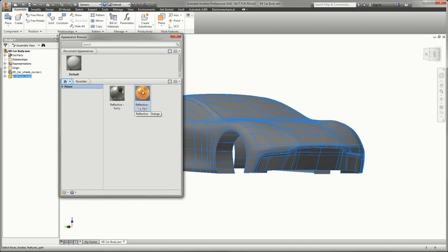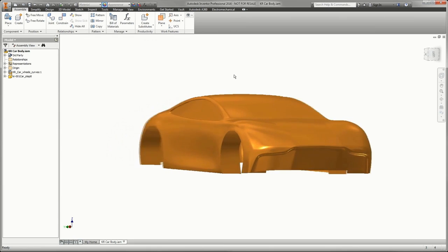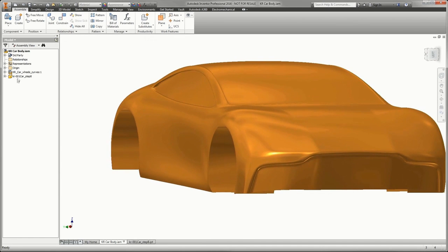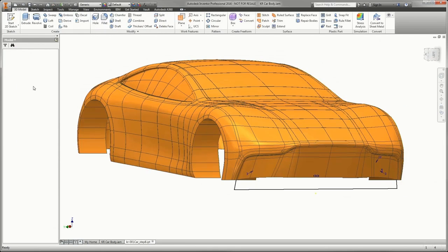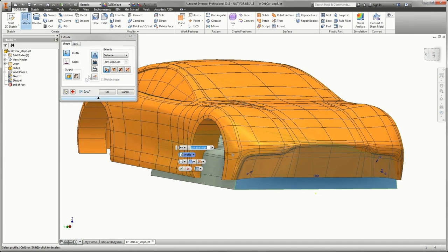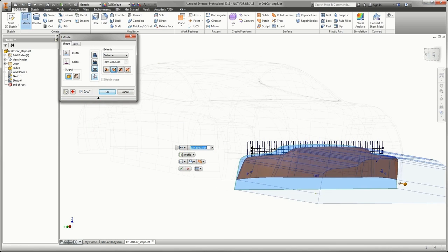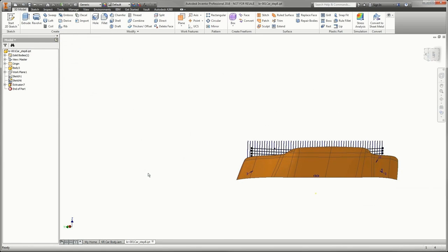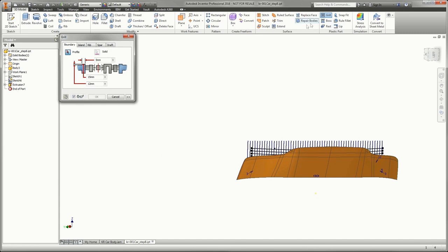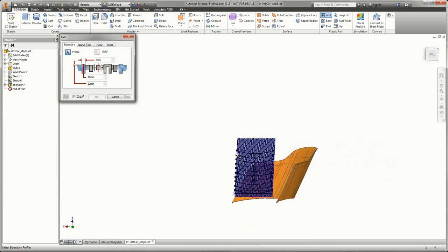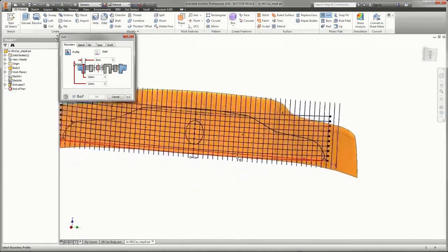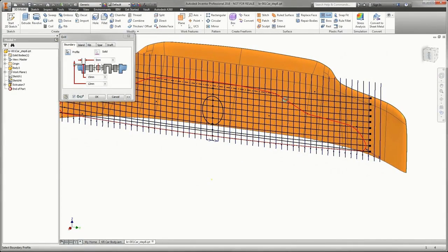It's thickened to 2 millimeters. And what I'm going to do here is start to work on the grill structure. There's some plastic feature capability inside of Inventor, so even I was able to figure out how to do this. I ended up cutting out the section that I'm interested in, and then I'll turn it around and start the process of grabbing the pieces to create a grill structure in there. When it gets all done, it is an Inventor part with the grill, but I can take that grill out, bring it back into Speedform, and start to use that to keep on working.